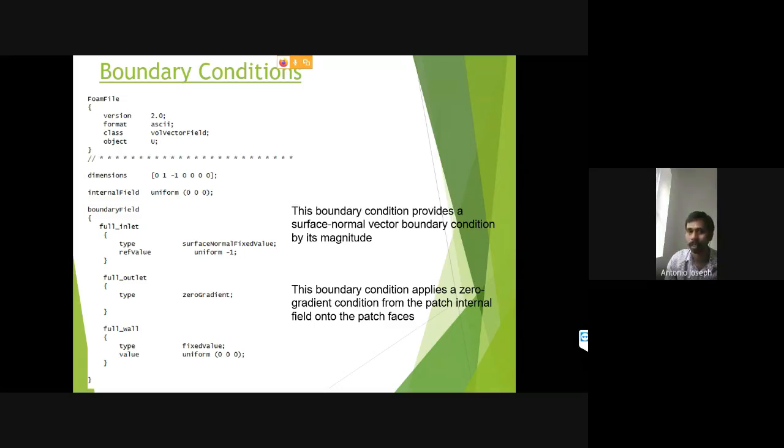So what we do is either specify velocity at the inlet or outlet, and the pressure should be specified at the opposite one. If I am specifying velocity at the inlet, I need to specify the pressure at the outlet. Accordingly, the pressure will be calculated for the inlet, and the velocity at the outlet will be calculated according to the pressure value at the outlet. Thus we will reach the correct solution.